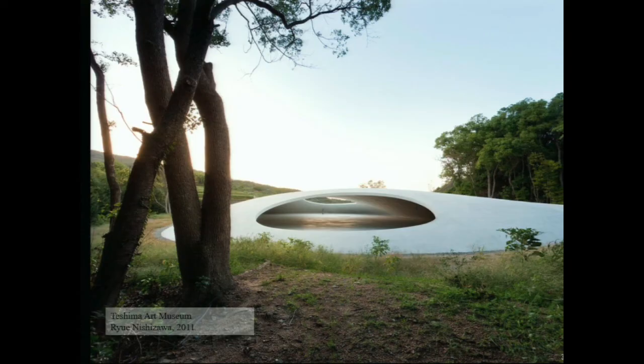Now, the previous example, albeit arbitrary, shows the potential of the workflow to design shells with large apertures in a structurally mindful fashion. For example, this project, which was designed in a highly seismic area, the position of the holes is incredibly important for the structural behavior of the architectural surface. The tool we developed allows to easily explore the position, size, and shape of these holes while ensuring that the structure is sound.